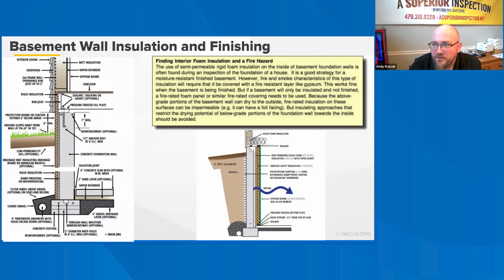Low permeability vapor retarders on the interior side of the basement finishes, like polyethylene sheeting and vinyl wallpaper, should be avoided as they trap moisture vapor moving through the foundation wall, hindering the drying process for new foundations. Unfaced fiberglass batt insulation and permeable paint finishes on gypsum wallboard are preferred for basement finish wall assemblies. Proprietary basement finish systems using rigid fiberglass insulating boards have performed well. However, certified installers may be required by manufacturers. Rigid foam creates a moisture-resistant material buffer between finish wall materials and the basement foundation wall.